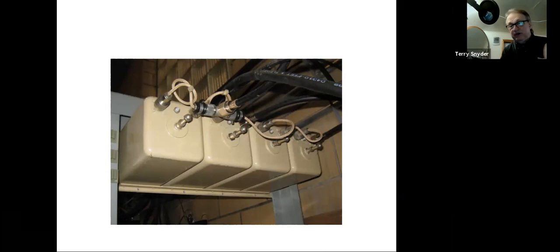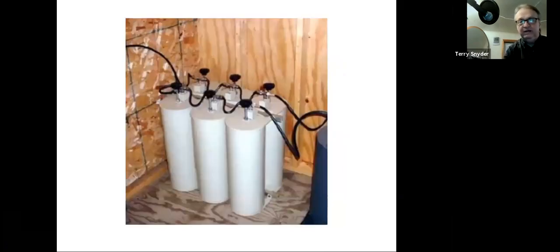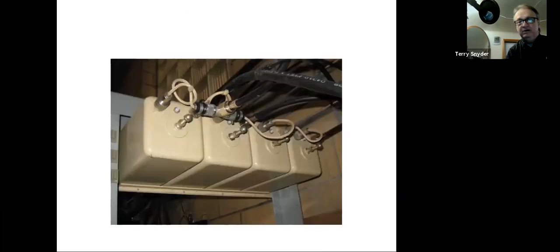If you can picture this, it's 19 inches wide. It's got 4 cavities instead of 6, because we only have, in the 2 meter, which we had here, you need a lot of rejection to keep that 600 kilohertz away. And these are big because of the frequency. In UHF, in the 70 centimeter band, they are smaller, and you don't need as many because you're dealing with a 5 megahertz away signal. So it's easier to deal with.